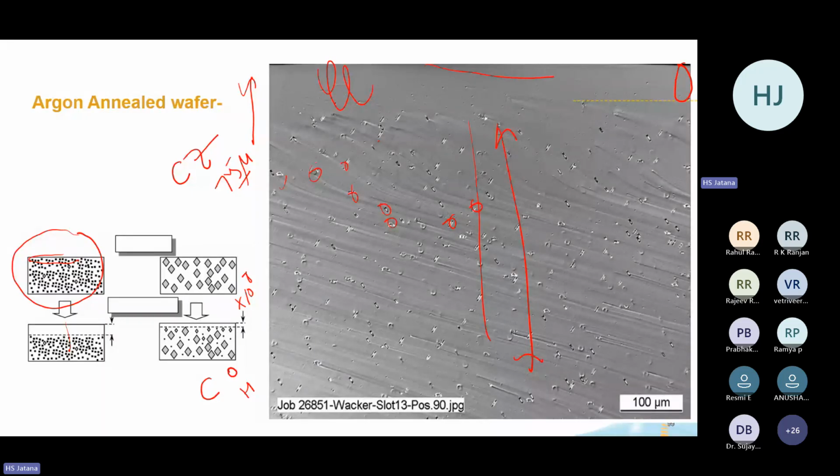is lapped. Lapping is a packaging process where the wafer is cut. I will cut the wafer from here, and I will use only this much area. On the top it will also add around 5 to 6 micron, depending on the number of metals. So the total will be a chip around 15 to 20 micron thick, which will be packaged in a very thin package. Nowadays, the TSOP packages are very thin outline packages. So that is how it is done.